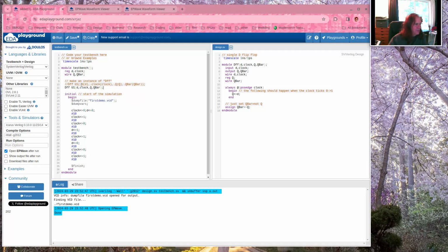And we don't need to do this business of naming the port that we're trying to connect to, right? By default, this first signal that we've named here will be connected to the first port in this D flip-flop, which happens to be D, and the clock will be connected to the second one, and so on and so forth. But if for some reason, instead of using the word clock, I wanted to just call this CLK, right?